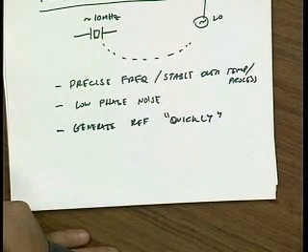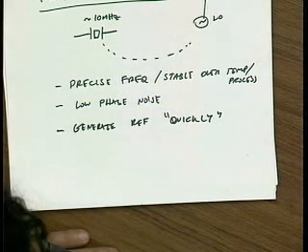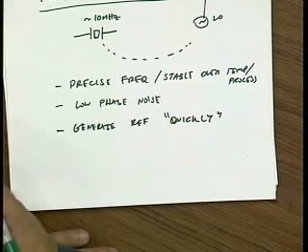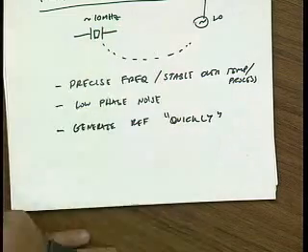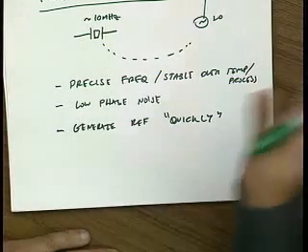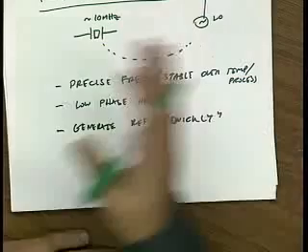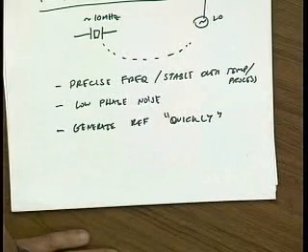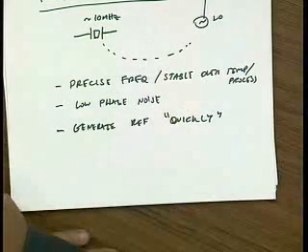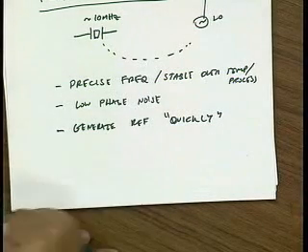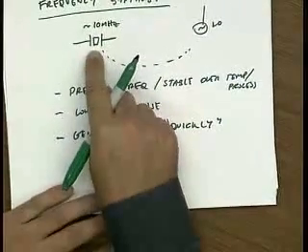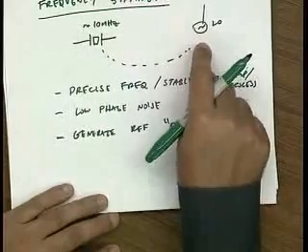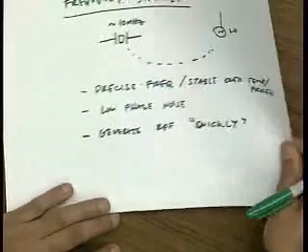You're at 1.001 gigahertz, you might go to 1.002 gigahertz, and you want to do that quickly. That might be because you're using a frequency hopped method of avoiding interference with other people, or it just might be you need to move to another channel because there's too much interference on a given channel. So we need a mechanism that lets us take this precise frequency and somehow control this oscillator.